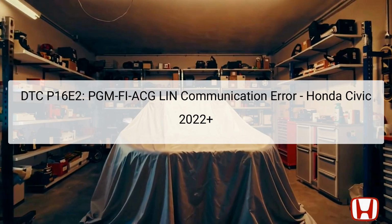The diagnostic trouble code DTC P16E2 specifically refers to a PGM-FI-ACG LIN communication error in the Honda Civic 2022 and newer models. This error indicates a malfunction in the communication line between the engine control module, ECM, and the alternator, also known as the ACG, alternating current generator. When the Powertrain Control Module, PCM, fails to receive signals from the alternator through the local interconnect network, LIN, it registers this anomaly and triggers the error code.